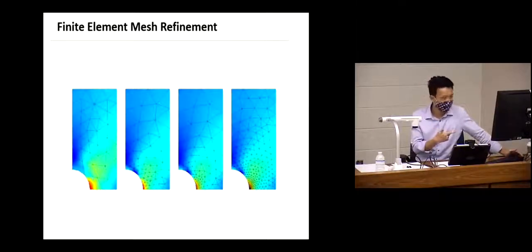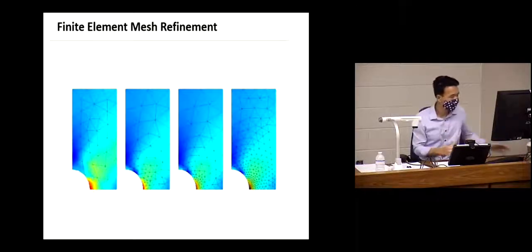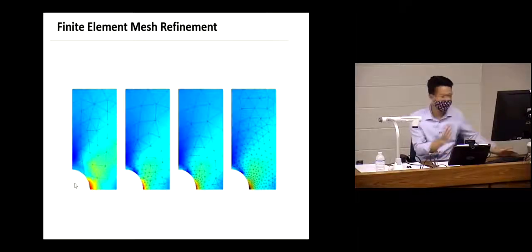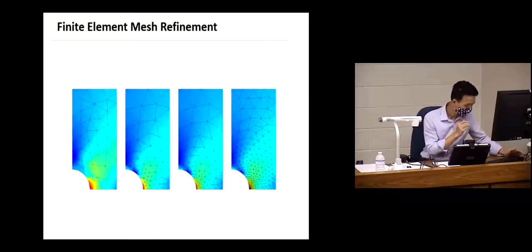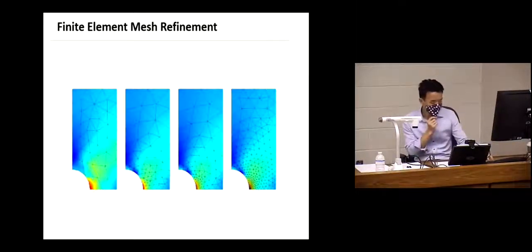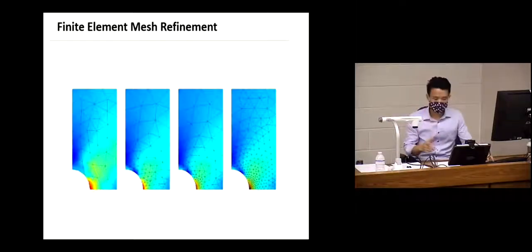But I want to point you to this because this is something that you may find useful. I have had students before who never get a good fracture stress intensity factor because their mesh is something like this, right? But if you're limited to 1,000 elements, you need to do something smarter, right? You lose some of the mesh density around here, and then you focus on here. That will improve your solution. Right, so that's mesh refinement, just one practical thing I wanted to talk to you about. Now, let's go back to the topic we want to talk about, which is the flaw size, okay?